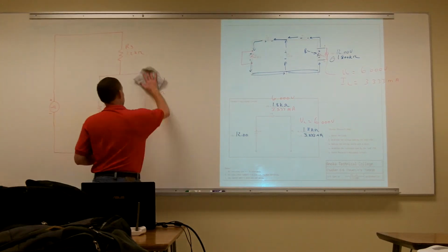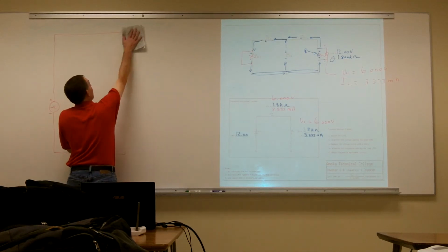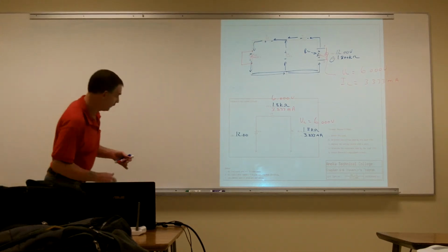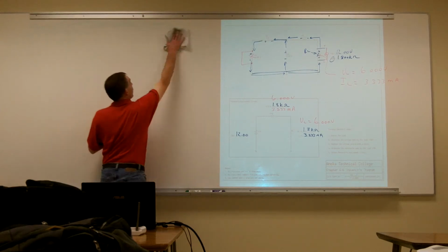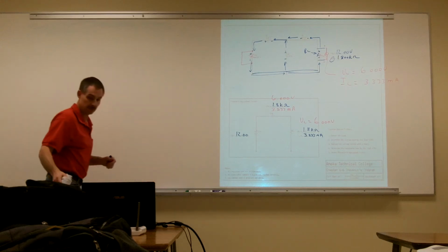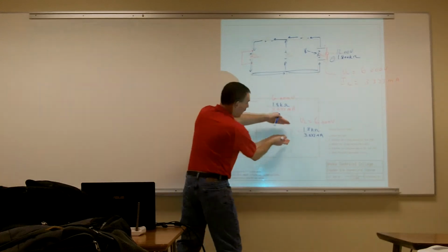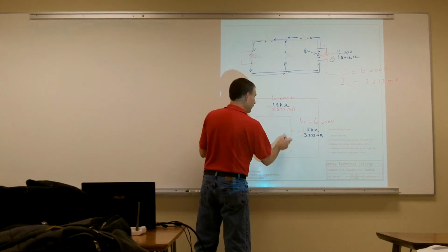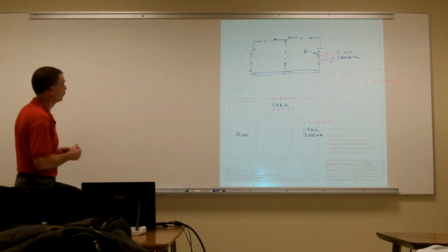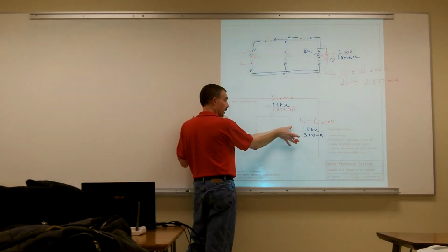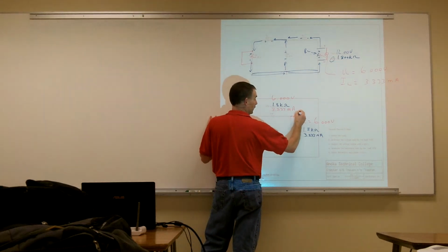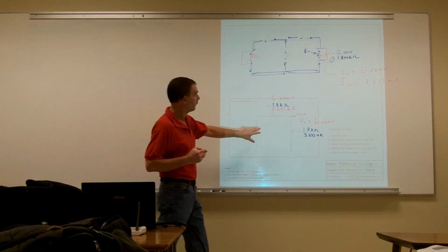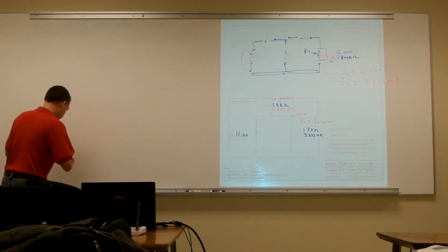So let's take a look at a little bit about that, because that's kind of an important thing. And that's kind of the whole idea of Thevenin's resistance, is to find out what our maximum power is, especially if we're into broadcasting wirelessly or whatever we're doing. We want to make sure we get the most amount of power coming out of our antenna, because this RL could represent an antenna, which is electromagnetic energy. It doesn't necessarily have to be a resistor. It could be an antenna, which is electromagnetic energy that's being put across the output of our device. So this would be our VL. This is our output terminal of our device. So let's take a look at that circuit a little bit deeper.